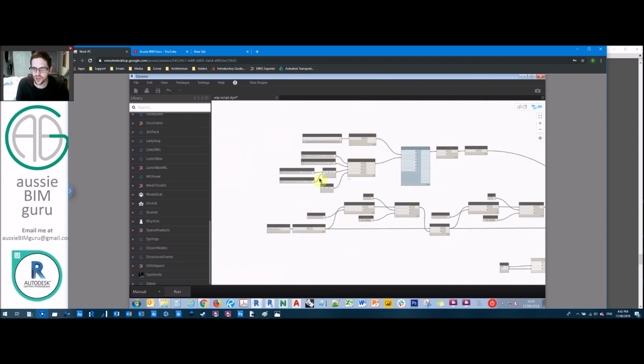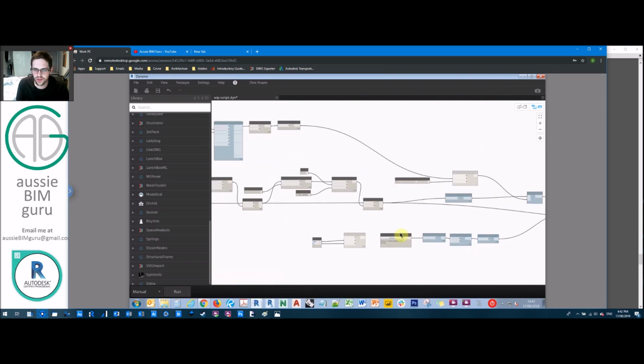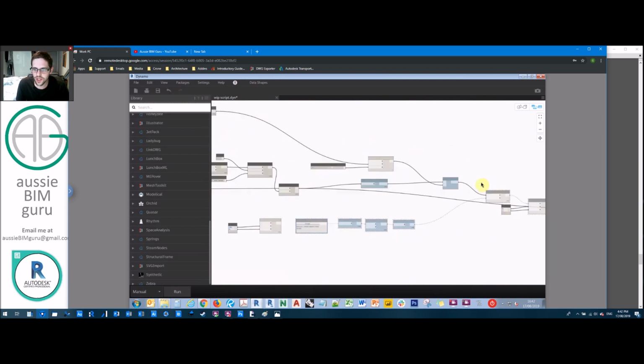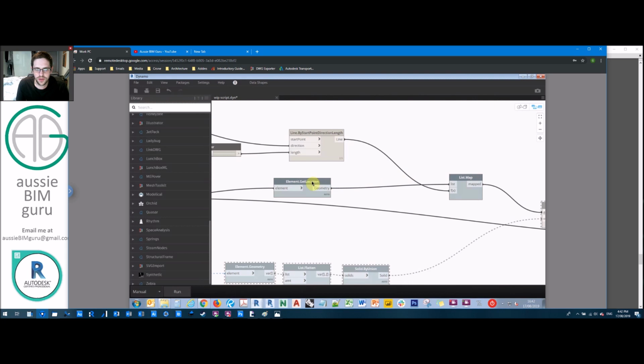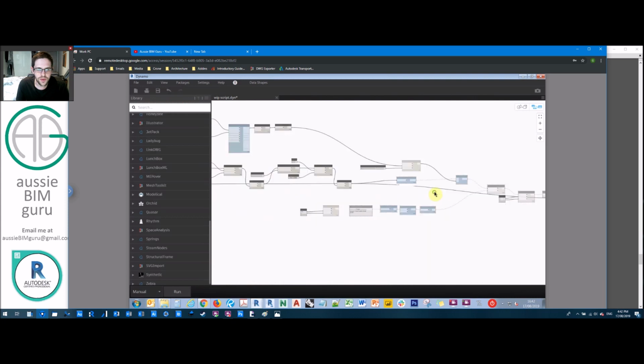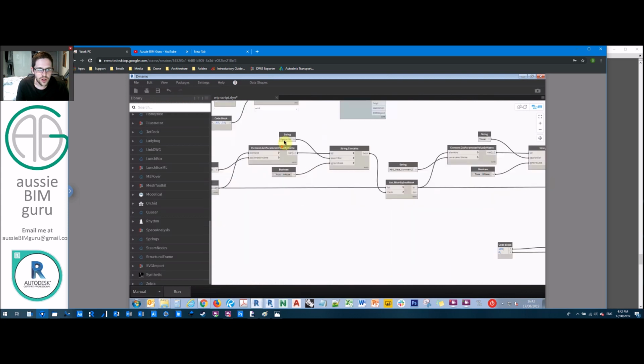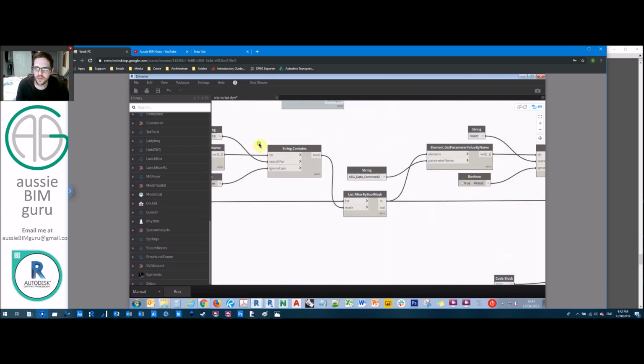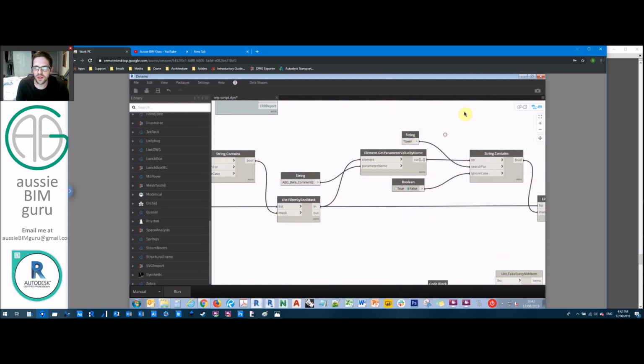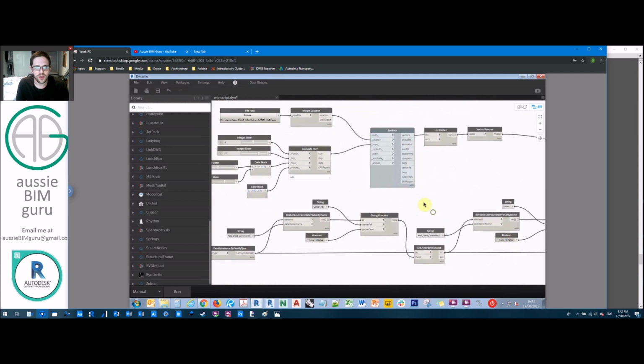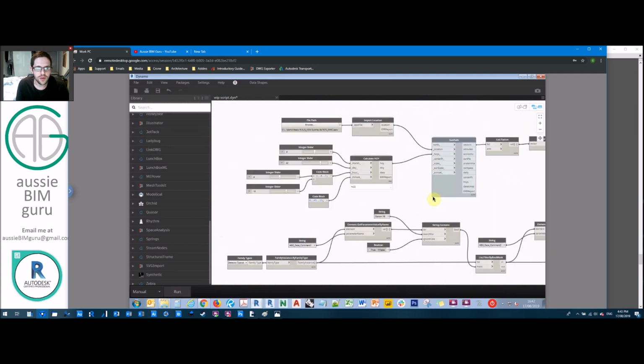What I'm going to do is jump ahead a couple of steps and freeze a couple of things. I'm going to freeze my model geometry, which essentially will freeze a majority of our script. I'm also going to freeze my element location for my nodes. It's important to note that we've already got option 1B being filtered out and also the tower component being filtered out. So I'm still retaining the data in my sensors in order to limit the number of sensors that I'm dealing with.